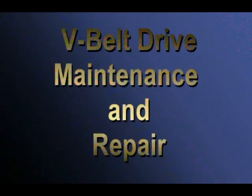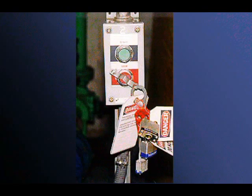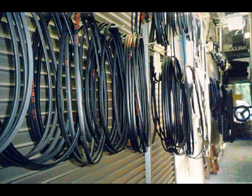V-belt pulleys, maintenance, and repair. Lock out the unit before beginning any maintenance or repair. The belt number found on the belt should be used to reorder belts, as there are many types and manufacturers of V-belts. If there is more than one belt, they must all be replaced at the same time. Purchase and install a matched set so that all belts will wear evenly.